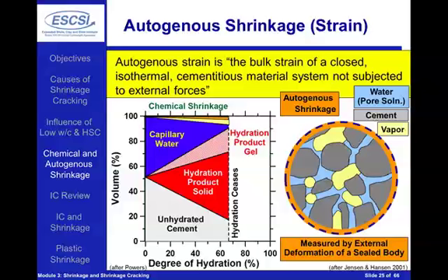Now, as I mentioned, the autogenous shrinkage is going to be a portion of the chemical shrinkage. So what is the remainder of the chemical shrinkage going to be made up of? Well, we know there's going to be a total volume reduction. However, after some point, the cement particles begin to impinge on one another, and the total external volume change can't be equal to the total volume change that's happening in the system. And what we will see is vapor-filled spaces starting to form inside of the matrix. These vapor-filled spaces shown here in yellow will give rise to this idea of self-desiccation happening in the system.